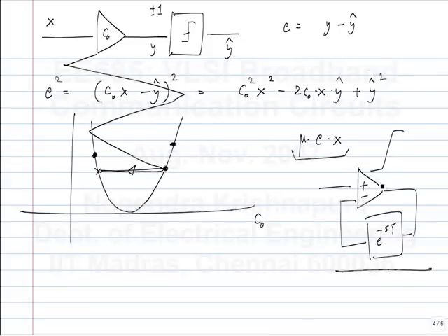In this particular case, if you have an op-amp with saturation, it will always oscillate. I am assuming that this is a memoryless characteristic, that is, it doesn't have any poles inside it, and it has saturation. And there is a certain ideal delay t. Eventually, because the gain of the op-amp is high, that's the assumption, it will always oscillate between 2 points in the saturated region of the op-amp. How fast it goes back and forth is determined by t. What will be the period of oscillation? 2t, right? Each one will be t. The output of the op-amp will be something like this, that's all.